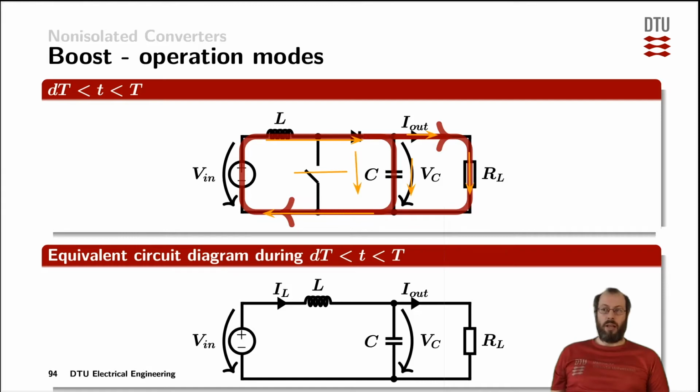As the diode transfers into a perfect short circuit, the inductor forms a second-order low-pass filter together with the capacitor and the resistor. Again, the right-hand side of the diagram is hardwired, and now the inductor feeds its current into the parallel circuit of capacitor and resistor.